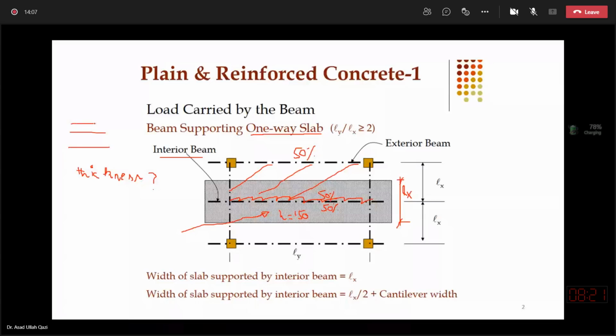We have the architecture working drawings, and from the section we got the idea that the floor finish proposed by the architect is of thickness 100 millimeter, which might be a composite of brick ballast and terrazzo or some PCC and tiles. So it depends on the selection of the finished materials which are superimposed on the slab.